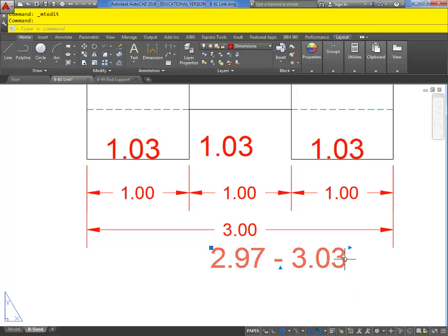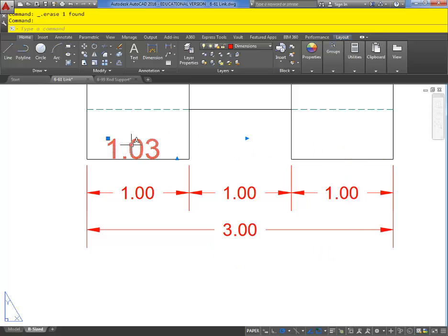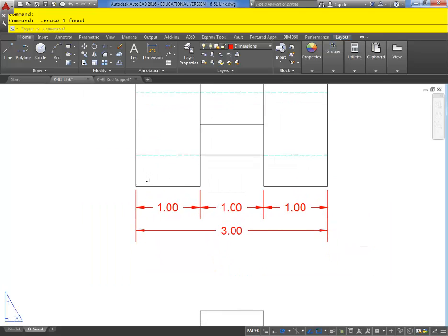So the way that you fix this is when you do a chain of dimensions, you leave one out. So maybe based on the way I cut, maybe I'm going to come over from the left 1 inch and cut here, and maybe from the right 1 inch and cut here, which means I'm going to be measuring this value and this value, which means I'm going to leave that one out. Or maybe, if you think about a table saw, how it has a fence and you measure everything off of that, maybe the left side's the datum and everything is measured off of there. So instead, I'm going to leave that dimension off. So it really depends on how it's going to be manufactured, and that's why we require a machining class, just to get an idea of how some things are made for the machine drafting majors anyways. But that helps determine what dimensions we want to leave on there. But more importantly, we want to leave one off. Does that make sense why?